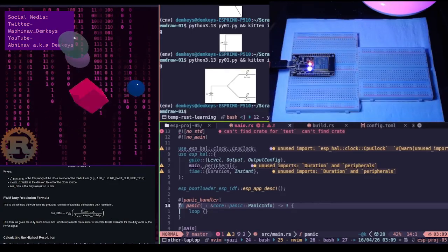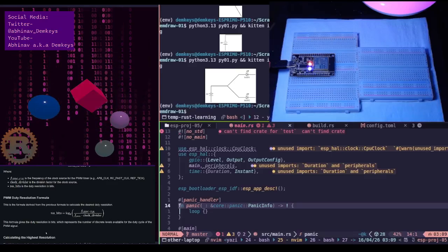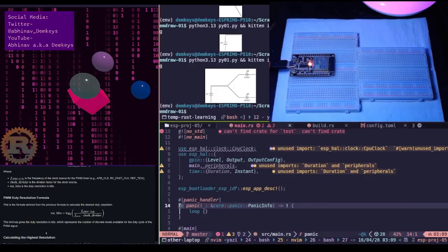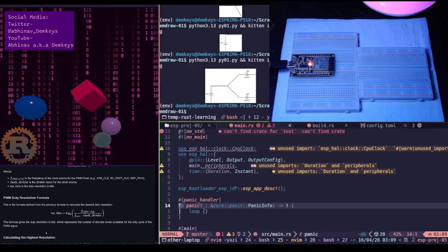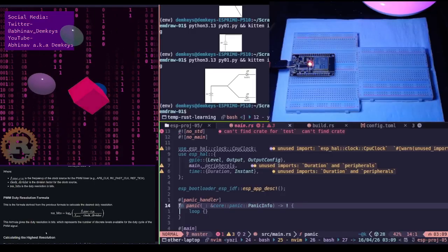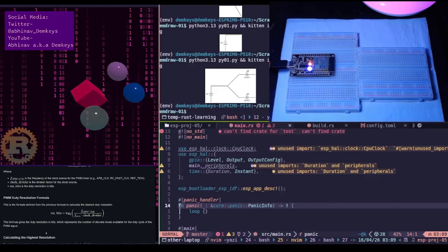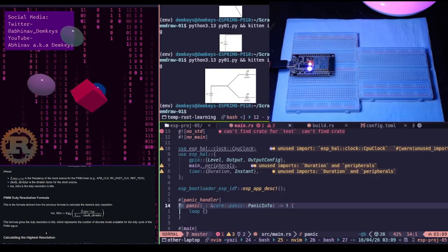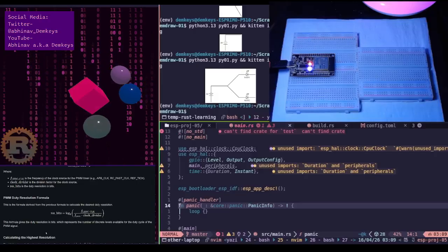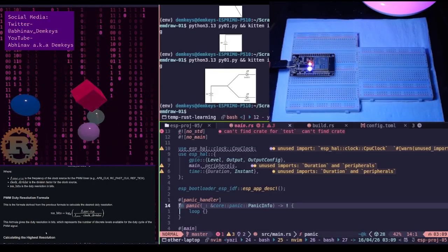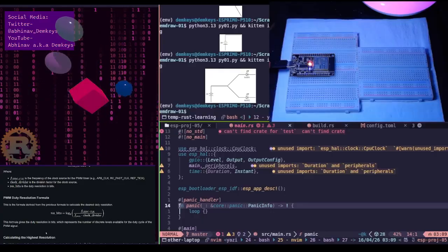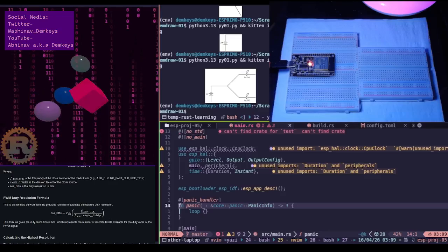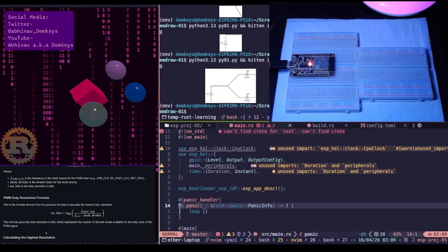So the ESP32, at least from my understanding, has no notion of time. The way that it measures time is basically in ticks. You have a clock signal being generated. Even the hardware that is meant to be reacting to time-based events mainly reacts to these clock signals, more specifically either the rising or falling edge of the clock signal. That is what synchronizes different actions.